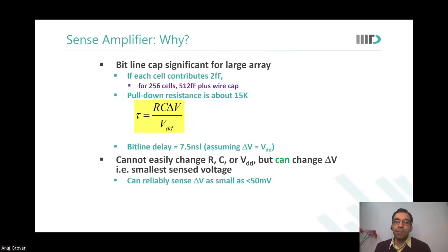But with a sense amplifier, I can precharge the bit line and discharge it only by 100 millivolts, and still be able to read correctly.